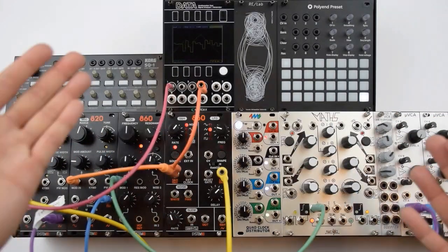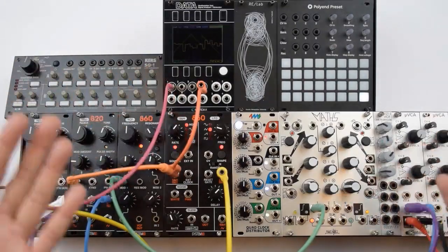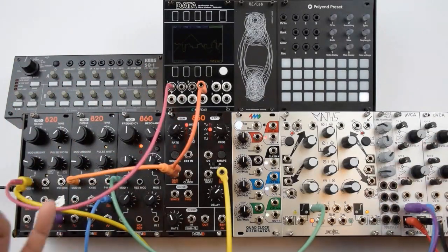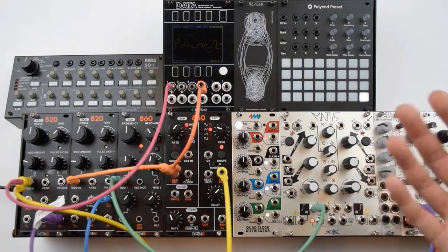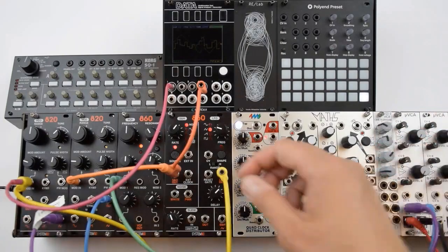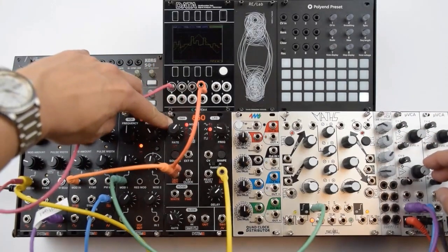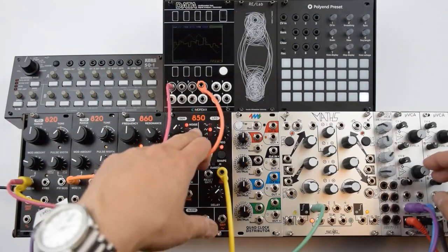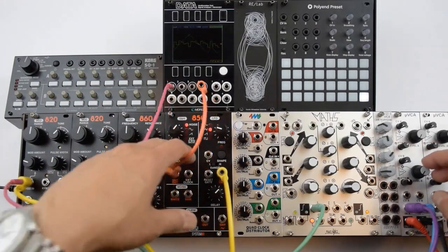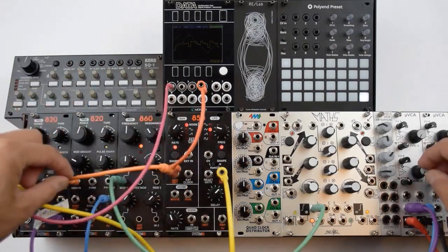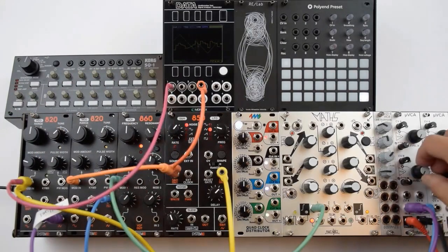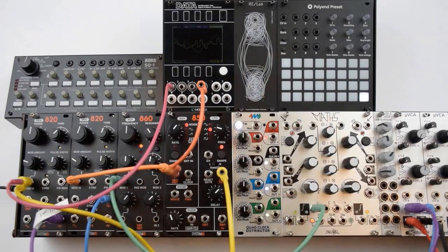And what happens with noise being fed into a sample and hold is that it creates a random stepped voltage. Here with our sample and hold circuit, having this built-in noise as an input source and then feeding it into our second oscillator, we get a random step sequence.